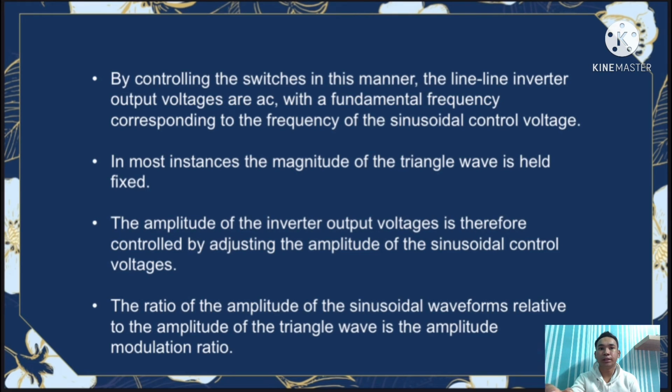Then by controlling the switches in this manner, the line to line inverter output voltages are AC, with a fundamental frequency corresponding to the frequency of the sinusoidal control voltage.